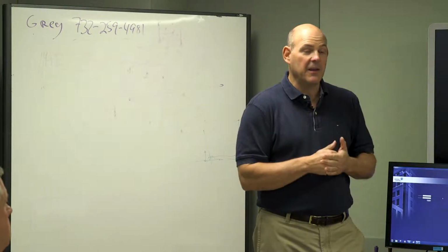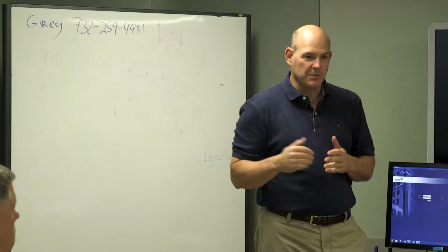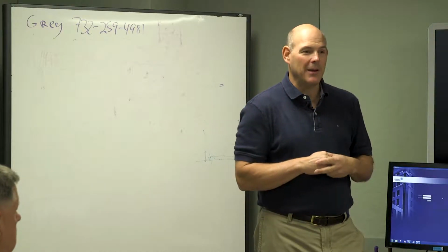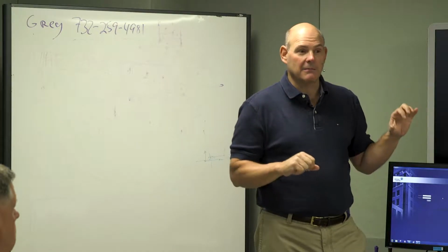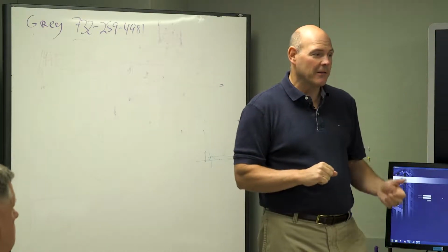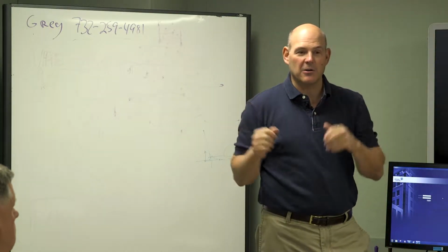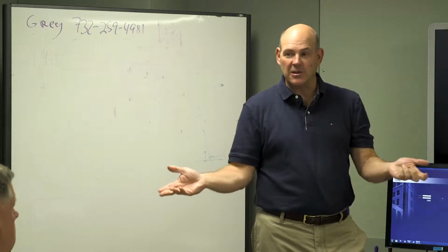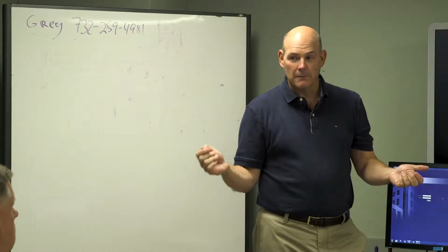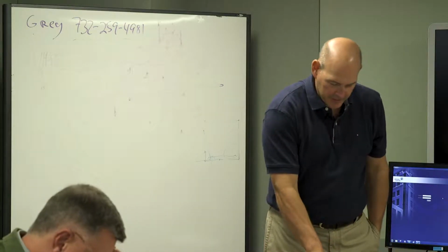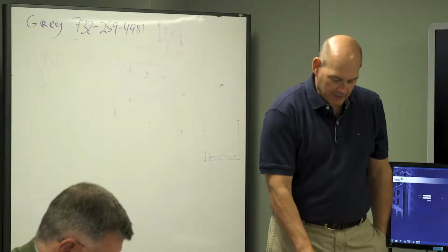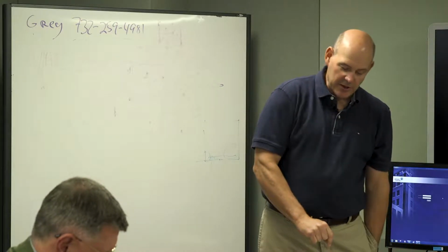One thing is, if a VFD fails and it ramps up to 100%, well, maybe it's not reading DP. DP says 0. So all your pumps keep coming on and ramp to 100%. First thing you're going to look at is your DP transmitter, right? If you look here on the graphic for the pumps, in the middle all the way to the right, there's your DP transmitter.